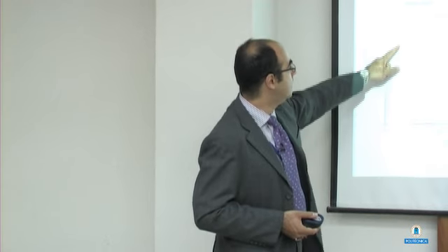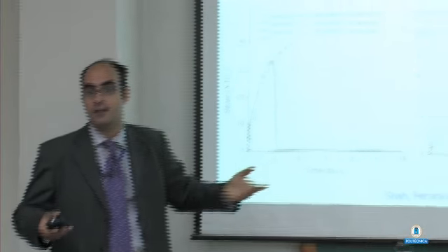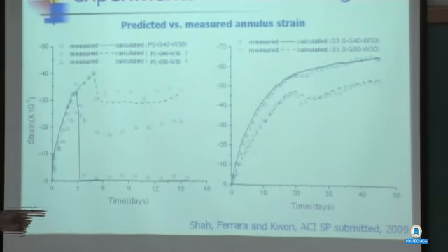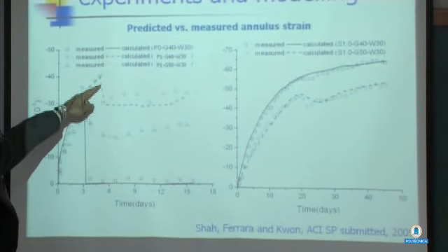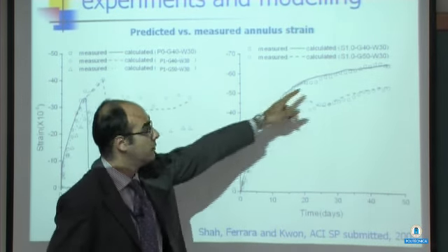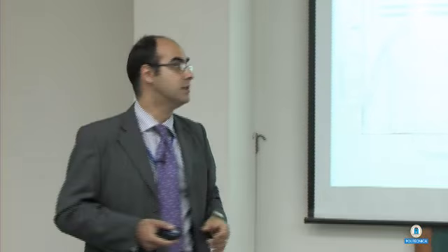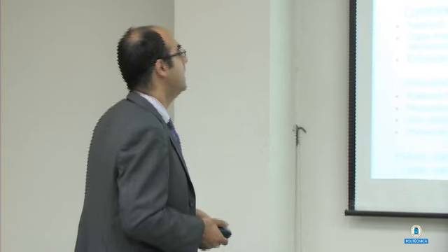You can see here with the plain matrix at a certain point the strain in the steel annulus decreases. When the crack is formed, there is no effect of confinement. With polypropylene fibers you have a decrease, but the steel always remains active, while you can see here with the steel fibers the effect always remains because the crack opening is still very small.